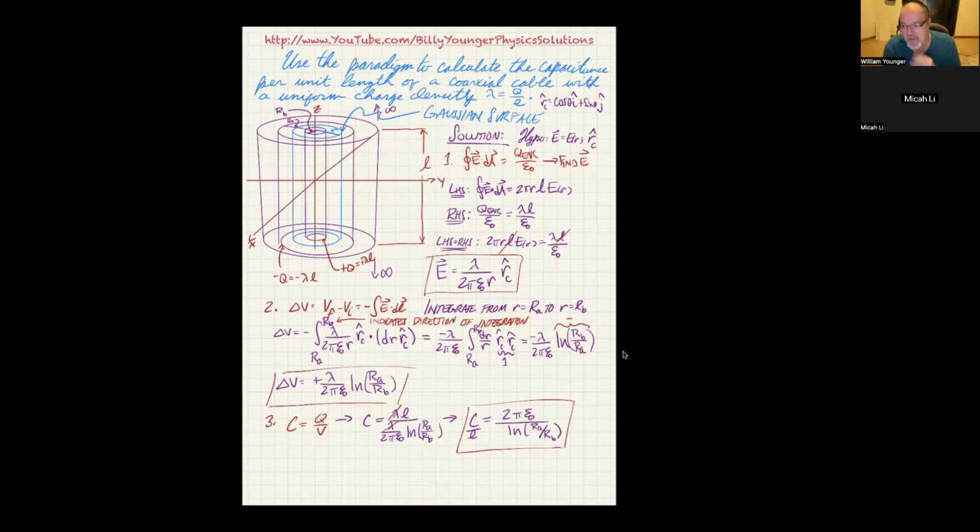Now we're doing the Thevenin equivalent. Thevenin and Norton, that's what I missed last class, so we're starting that. It's a neat little thing. It's called a Thevenin equivalent and a Norton equivalent, and it just allows you to treat every object like it's a power source with a resistor, so you don't have to know the details.